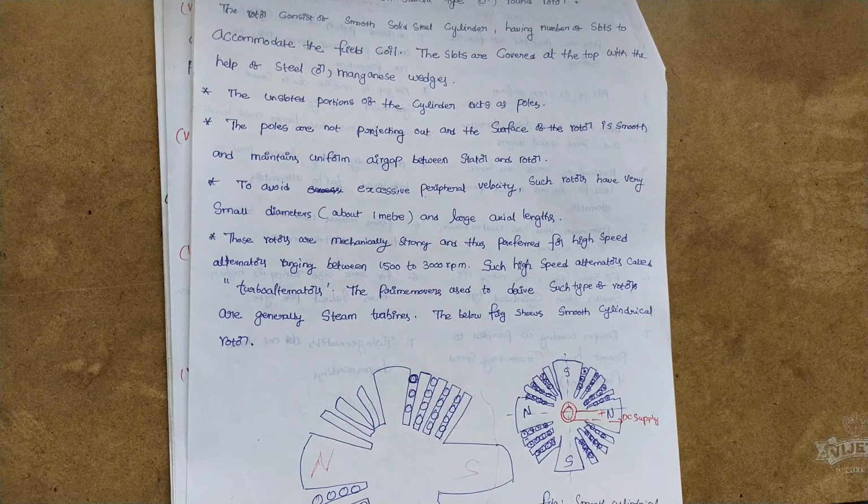Single layer winding means only one coil side per slot. Single layer winding is used only in small AC machines, whereas double layer winding is more common above 5 kilowatt synchronous generators. Above 5 kilowatt we have to go for double layer winding, because the higher currents have to be withstood by the stationary armature, hence we go for